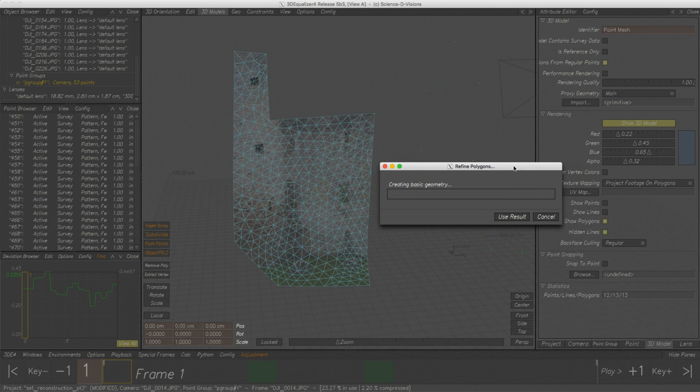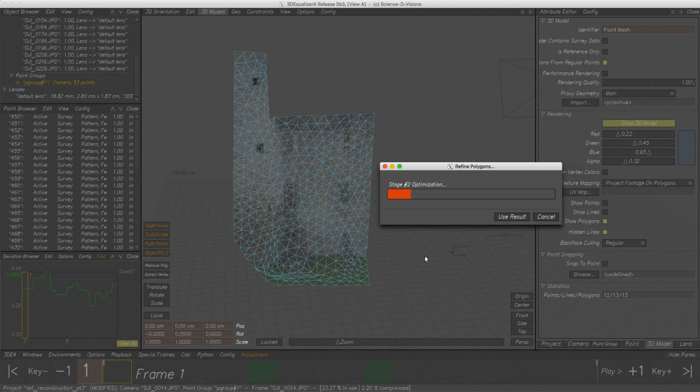We instantly see the original mesh was subdivided according to the set edge length parameter. The refinement process in this video was sped up to demonstrate better how the refinement works. Typically, such a refinement needs around 2 to 3 minutes. This high speed gives us the opportunity to try different parameters for an ideal result. Okay, while I was speaking, we saw how the 3D positions of the added vertices are optimized, leading to a good reconstruction of real-world tower and wall.